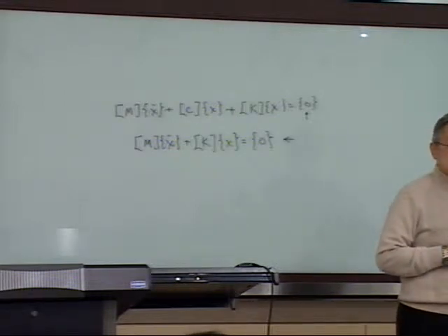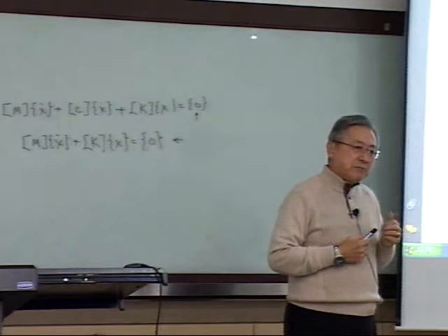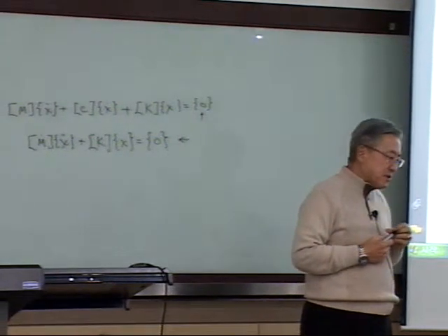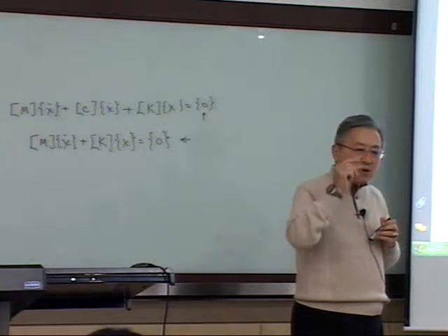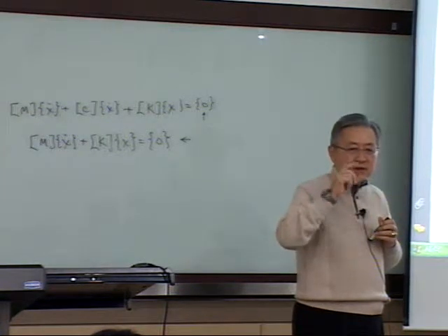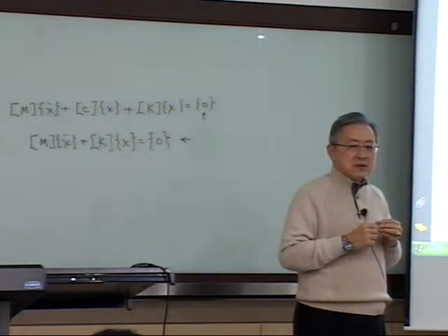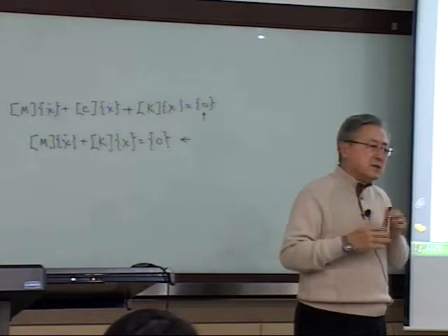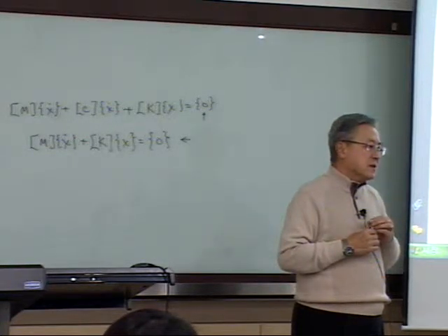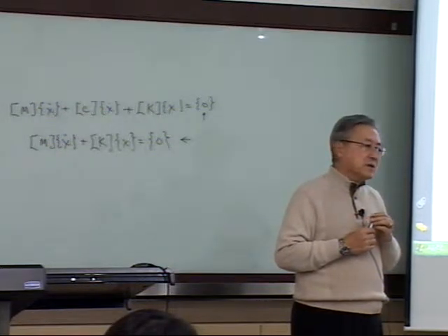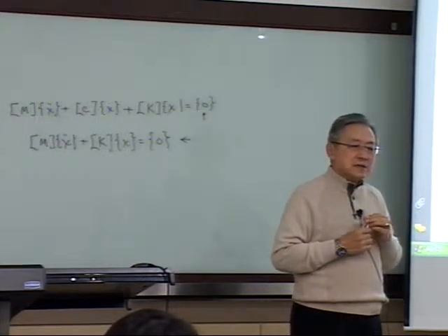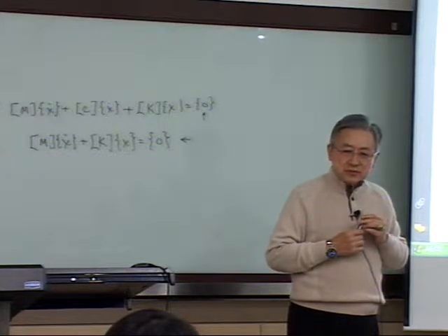But between the damped natural frequency and the undamped natural frequency, the difference is a small fraction of 1 hertz, even less. So you don't have to really calculate the damped natural frequency.